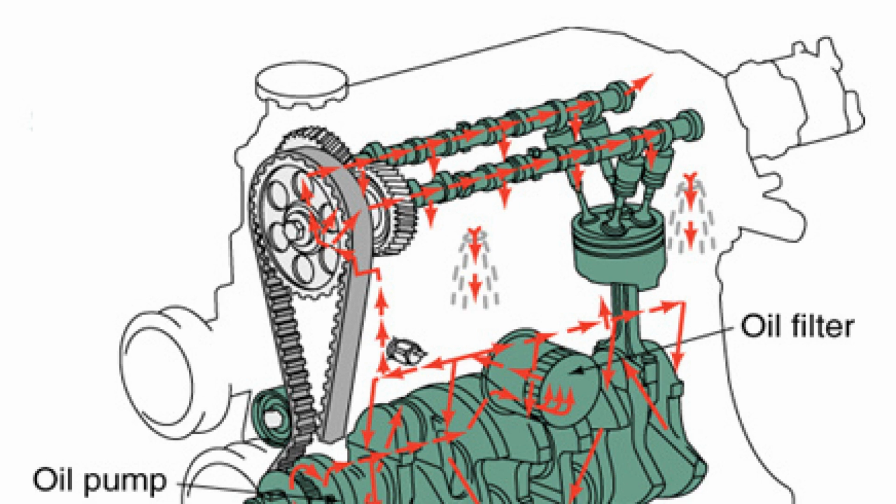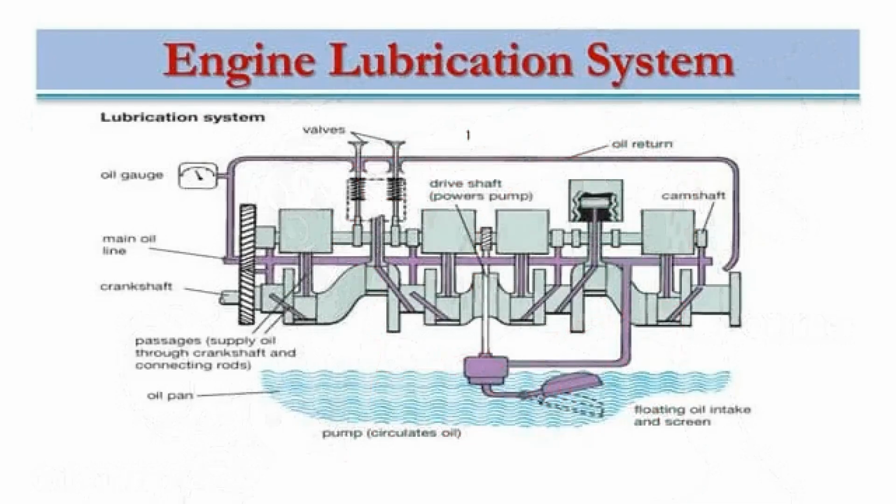Classification of lubrication systems. There are several criteria according to which internal combustion engines are categorized. In particular, according to the method of lubricant supply to the power unit parts: under pressure provided by the operation of the oil pump, by splashing method, combined method. Oil supply to the rubbing parts under pressure is necessary if no other method is possible to ensure accurately dosed delivery of lubricant to the part in a unit of time.